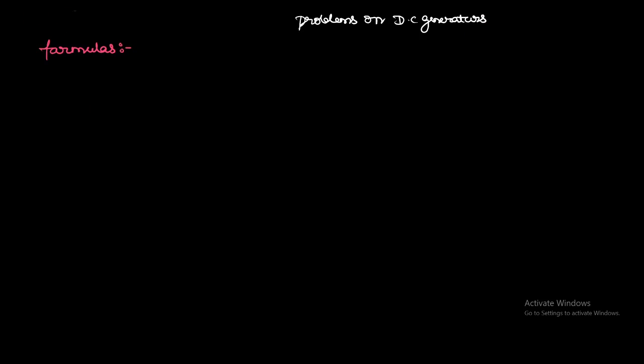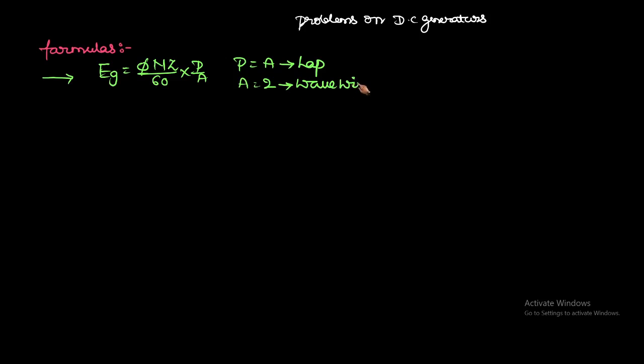First formula: Eg is equal to phi N Z by 60 into P by A, where A is equal to P for lap winding and A is equal to 2 for wave winding. We have already seen this. This is the EMF equation of a DC generator.